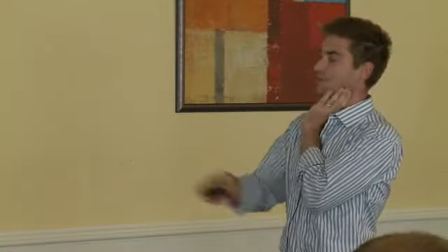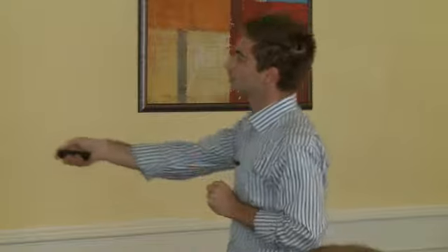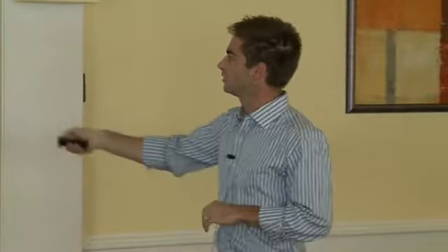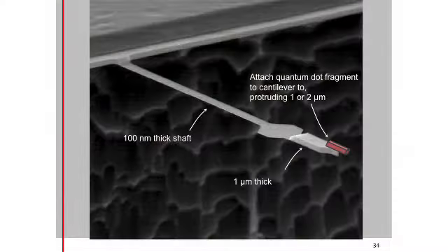Okay, so in our first efforts to do this, we've been trying to see if we can stick semiconductor nanostructures and heterostructures on the end of our cantilever in a similar way to the viruses that were on the end of our cantilever at IBM. The ideal would be if we could have our cantilever that I show here, and then cut out a little piece of a gallium arsenide wafer, maybe containing some quantum dots or a quantum well, and attach it on the end. What we really want is the interesting part of the sample, let's say the quantum dots or the quantum wells, to be as far out from the cantilever as possible, or as close to the magnetic tip as possible.